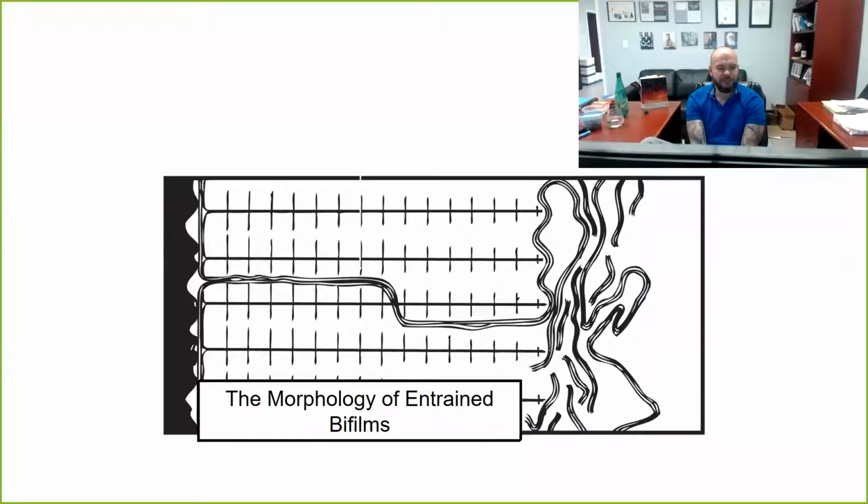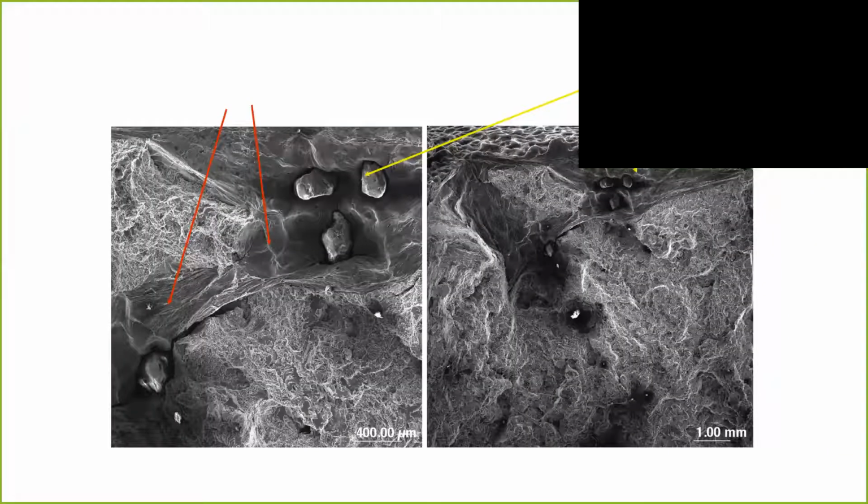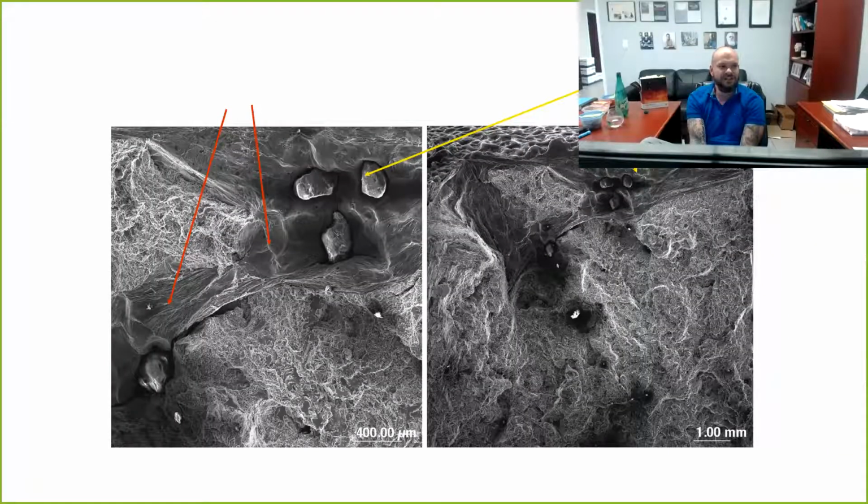During the solidification process, we talked earlier about those advancing dendritic tips pushing the oxide films into position and creating heaps of them. So that's that type of thing. Here's some example of individual grains of sand being trapped within an oxide film on a fracture surface of a casting.